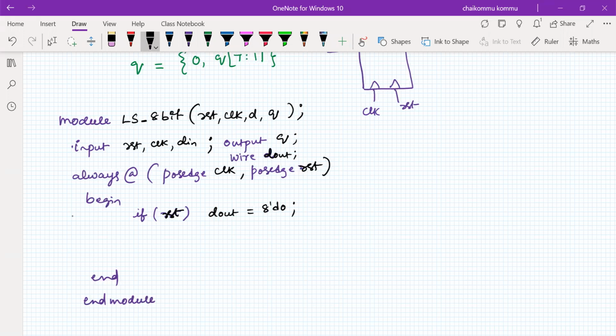Okay, if the content of the flip-flops is not equal to 0, what will happen? Unknown values will be there. Whenever you are shifting, all the time you will find unknown only. So that means you have to shift 8 times, then only the 8 zeros will come into the picture. But instead of using 8 clock pulses to clear the content of the flip-flops, by using the reset signal, in one shot all the flip-flops will go to 0.